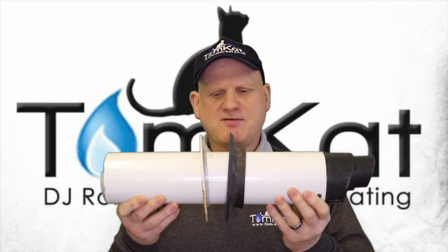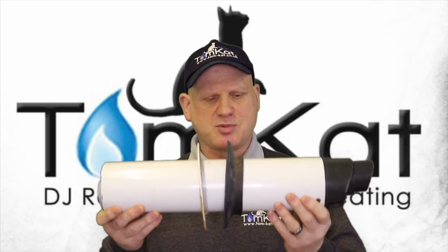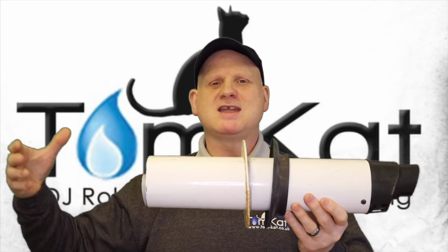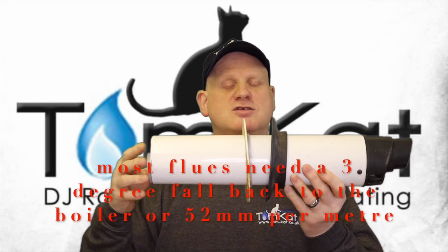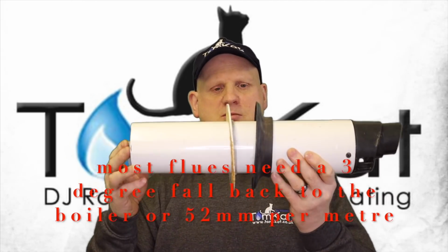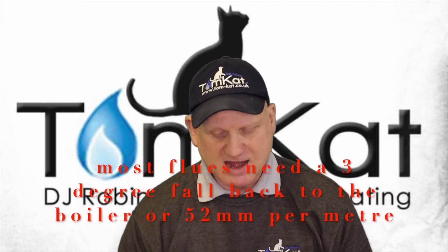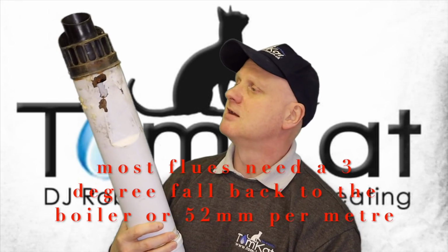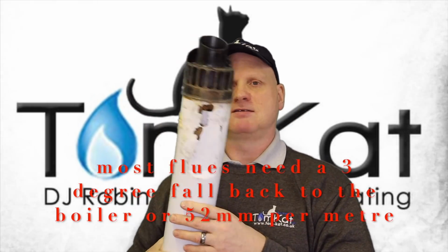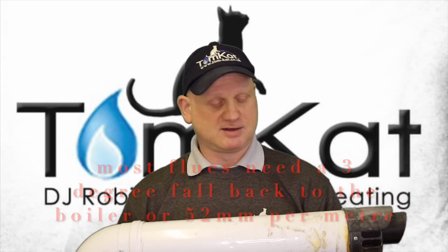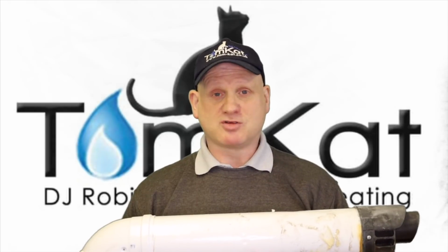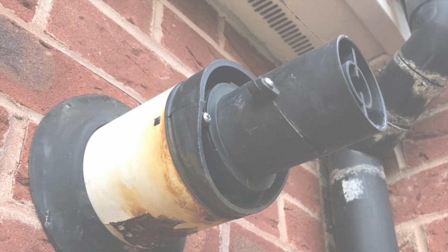So you only ever put a fall on a condensing boiler flue if you're using extensions and making it longer than the standard flue length. But if you're using the standard flue length, you put it perfectly straight. And that will stop things like this happening, rotting away, if you don't stick it out of the wall too far. So don't stick it out too far, there's no need.